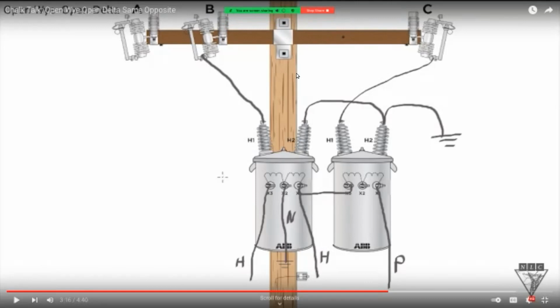Does anybody know where Oliver's is up there in Red Hill? Yeah, it's a perfect example right there. Oliver's is pretty much an all-electric single-phase place, but he's got 1 air conditioning unit in there. That thing is huge. He keeps that place about 68 degrees in the summertime. So all he needs is just 1 run of 3-phase to power that air conditioner. And you'll notice if you drive by there, look at the pole that's outside the complex, there's an open delta bank just to power his air conditioner out there.